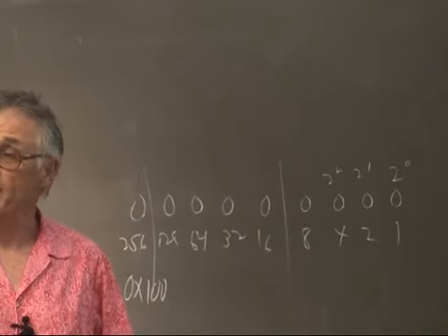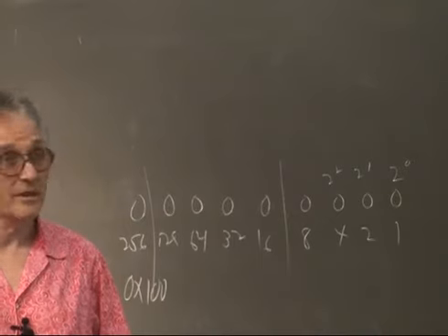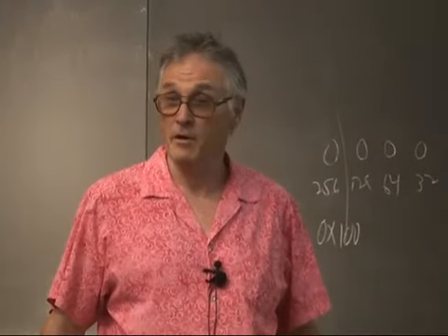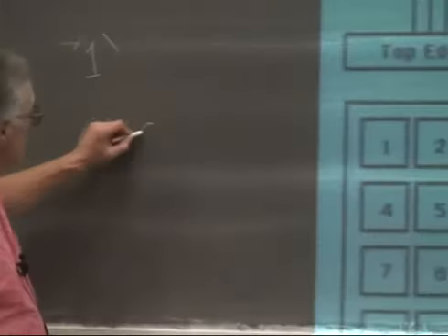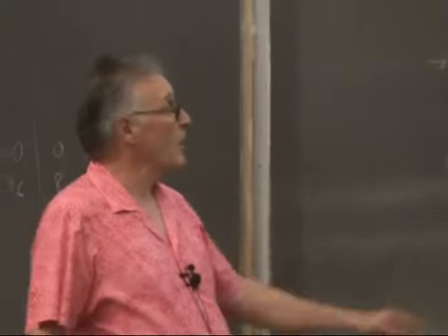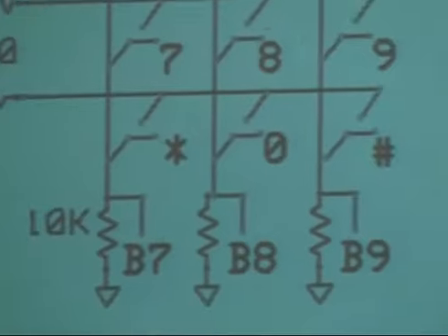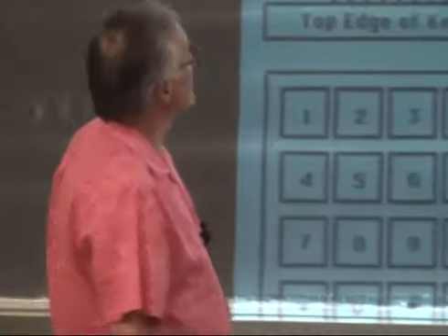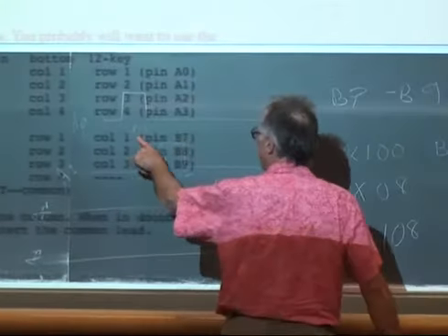What is the value of bit 7? Don't remember hexadecimal. So sad. 0x80. Exactly. So it's going to be the 8 here because bit 7 has a value of hexadecimal 80, and the low order bits are set by A, which is 1.